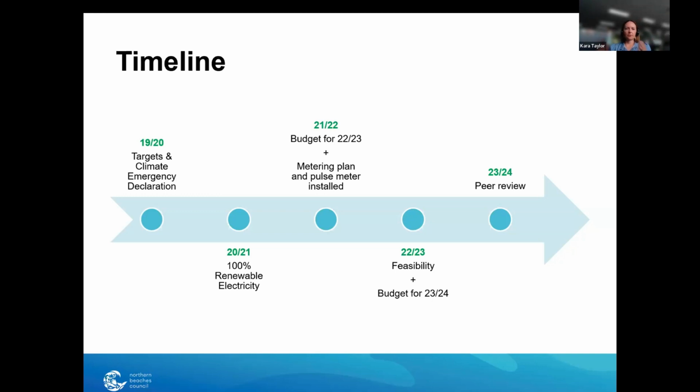We wanted to look at all the different types of heat pump solutions. So geothermal, wastewater sourced heat, reversible, were we close enough to the ocean? And also in that, what the refrigerant choices were for those, because that makes a big difference to what's going to happen with your emissions at the end. And like I mentioned before, probably my favourite part of the whole thing is the roadmap, because it gave me a really clear understanding of what I needed to do next and how long things were going to take and what was going to take the longest time for us.